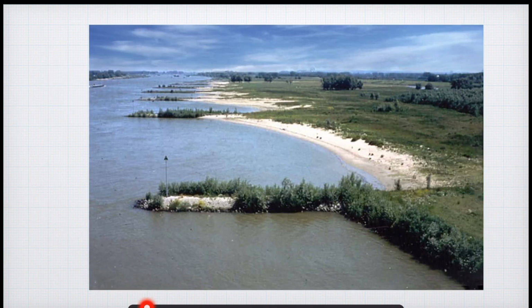These are examples of your temporary groynes. You can see these are made up of soil, and over that trees and plantation is done so as to ensure that there is no immediate erosion. These are not that strong, but do serve the purpose.